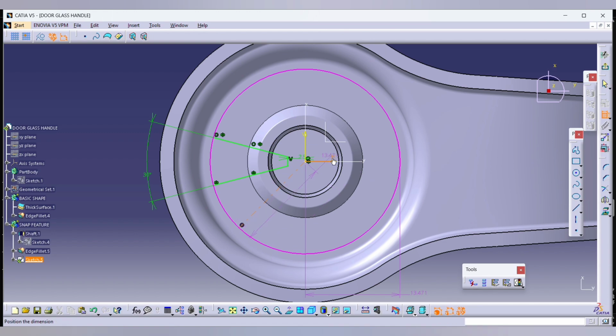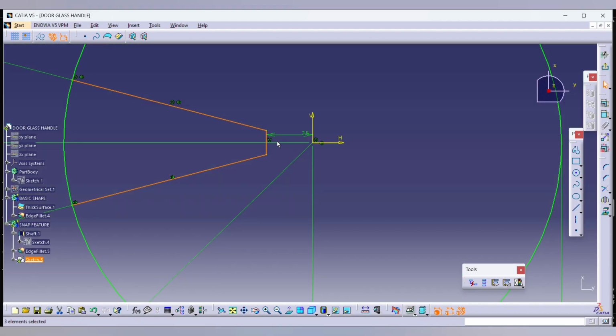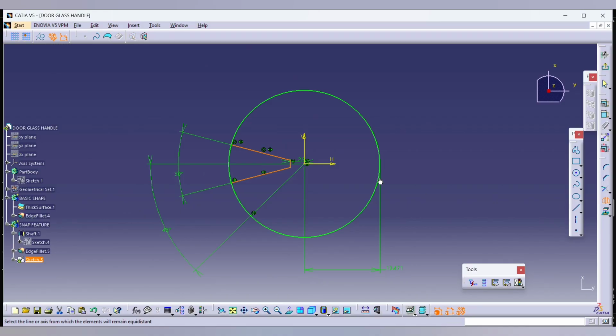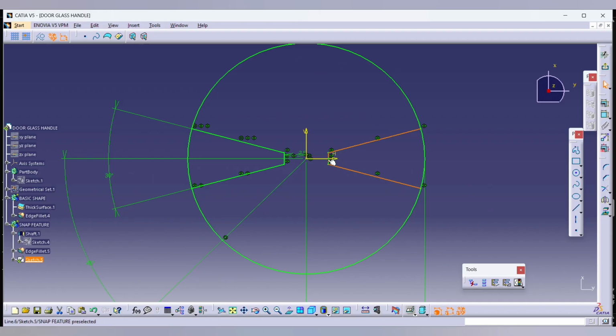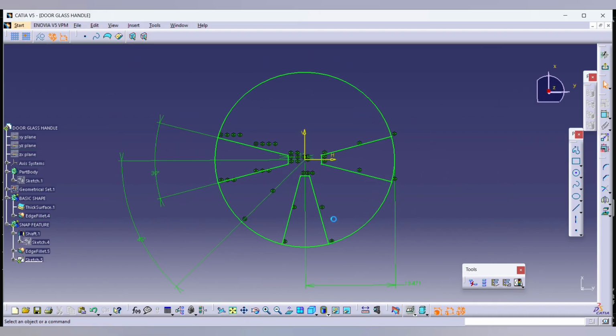we have to mirror this at the four sides. So firstly we'll mirror by 180 axis. Okay, so mirror command from vertical axis. After then we'll use the 45-degree reference which we made. Select all the lines, 45-degree axis. Yes, so we'll get it at the middle side, and we'll again mirror this from the horizontal axis. So here we got all the four pockets which we can take as a reference.